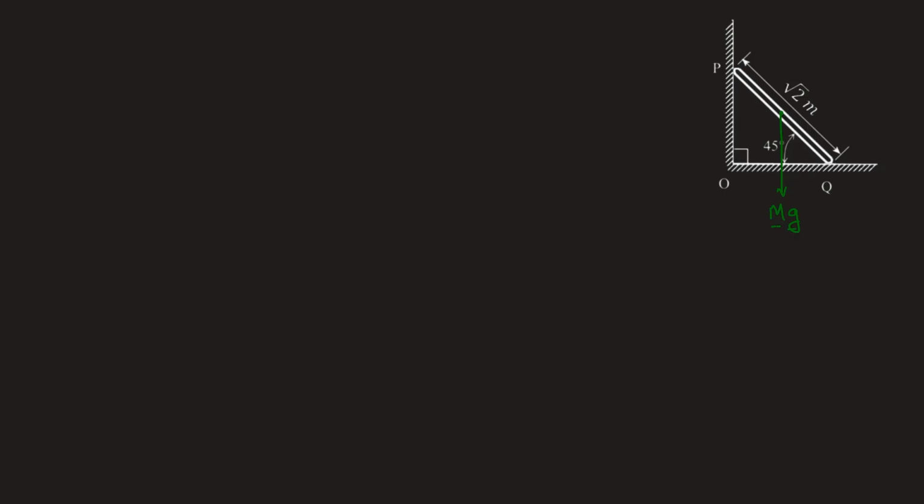The moment that is causing the rotation will be this Mg into this much distance. If we take the center of the rod to be R, then this distance can be calculated as QR into cos theta. QR is nothing but L by 2 into cos theta. So the moment that's causing the rotation is Mg into L by 2 cos theta.